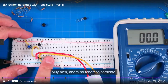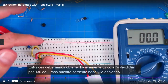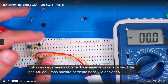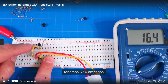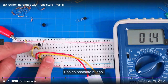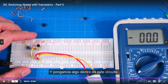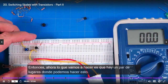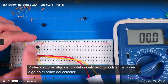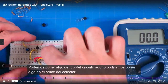Now we've got no current, and we're expecting about 3 times the current. So we should get basically 5 volts divided by 330 here, plus our base current. I turn it on, and look at that, we got 16 milliamps. That's pretty good. Now let's use that and put something inside of this circuit. There are a couple of places we can do this. We can put something inside the circuit here, or we could put something at the collector junction.